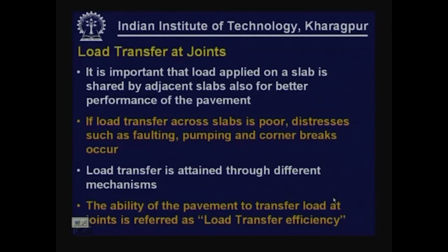We are usually concerned about the load transfer mechanism available at joints, and in most of the current design procedures, the efficiency with which load can be transferred from one slab to another is taken into account.